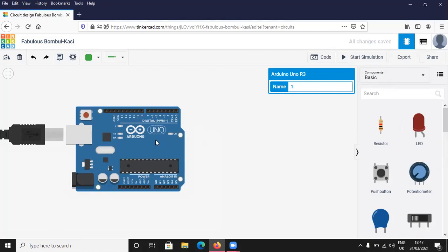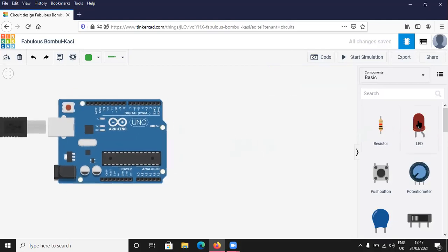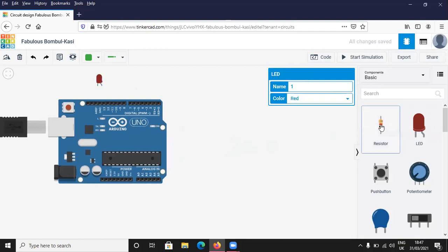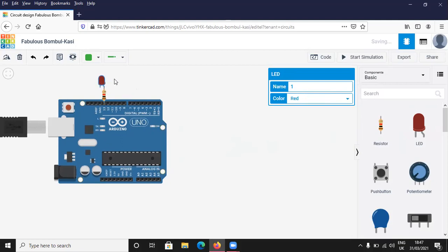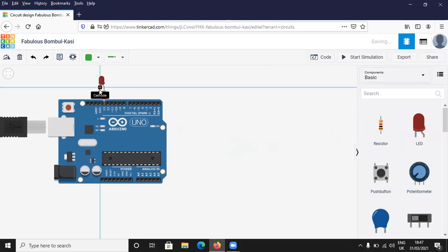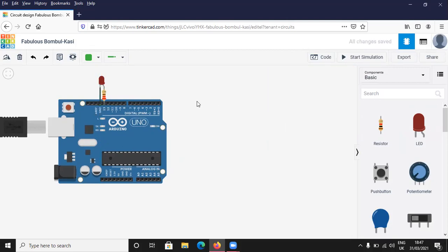This time I would want to start with the digital output to make it easier for us to understand what's happening, because it's very simple, this one. Make sure you connect it there, then you connect it through a resistor. I remember we said that a resistor is one of the most important devices as well, which we use to limit the amount of current. So we have 220 ohms there. And then you connect that to ground. You have it as black. So please connect your circuit that way.